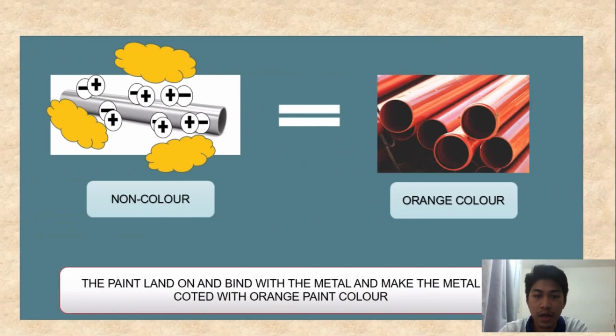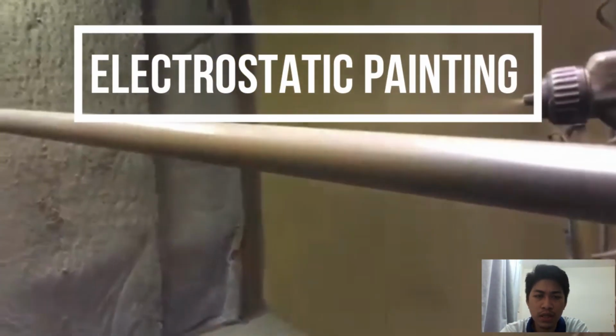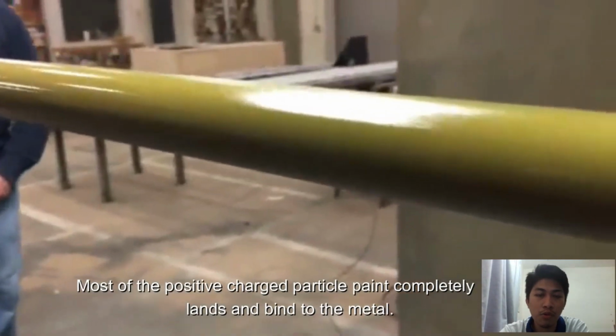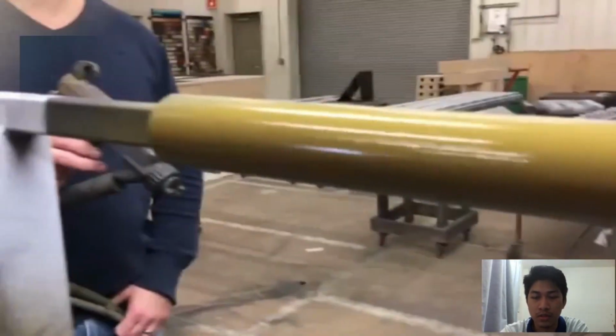Paint particles land and bond onto the grounded open surface area. As the particles coat the target, the charge dissipates and returns to the power supply through the ground, completing the electrical circuit. Because the surface charge of the target metal changes as soon as the bonding between the opposite charges occurs, the coated area stops attracting paint particles. The electrostatic process is complete with an even, high-quality application of the coating. Most of the positively charged paint particles completely land and bind to the metal.